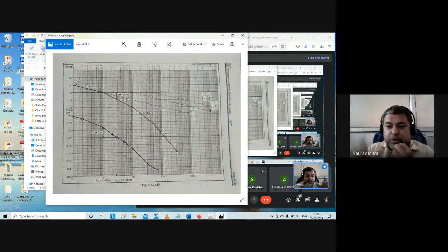So what is the sweet spot when amplitude and phase both are stable? The answer is in between omega gc and omega pc. So that is 1 radian per second up to 2.7 radian per second. That means only this much part is the sweet spot.